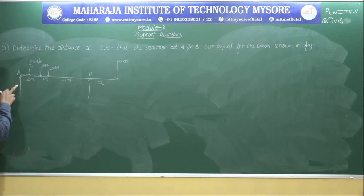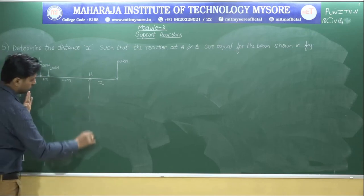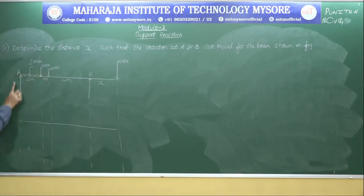Here they have not mentioned a particular symbol, whether it is a hinge support or a roller support. Whenever they give only an arrow mark like this for a support, just consider it. I will be writing the free body diagram first, because if you know how to write the free body diagram, almost think that the problem is solved. As this is just an arrow mark, you write that arrow mark and call it RA, because it's a vertical load. It's neither a hinge nor a roller as per the symbol.